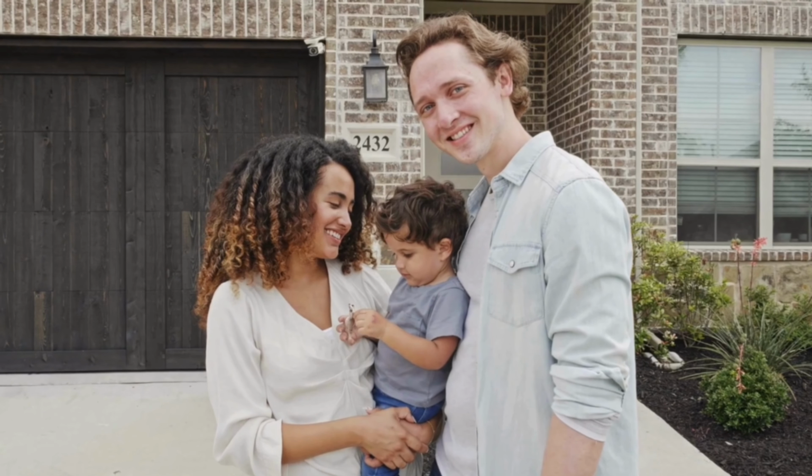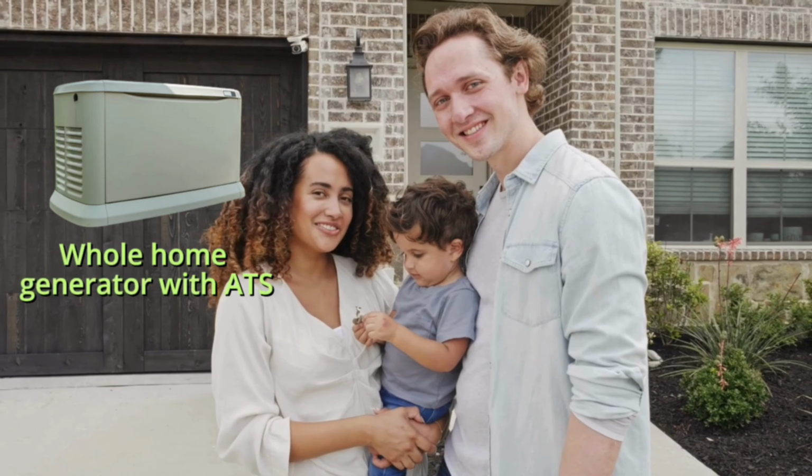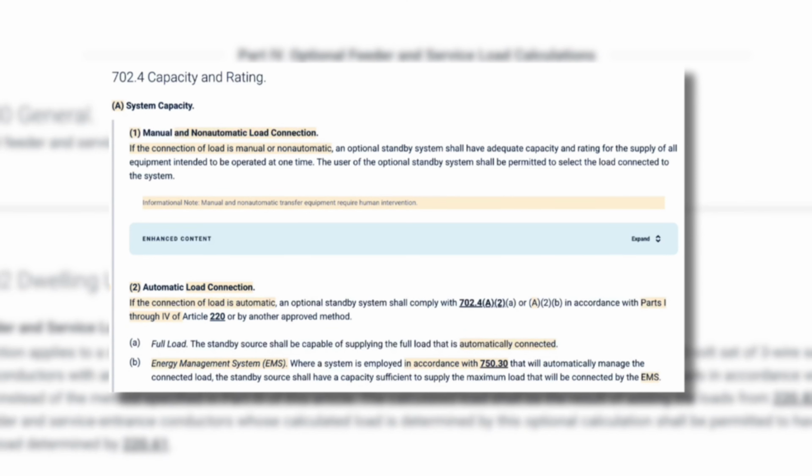Today, we're helping a homeowner in coastal North Carolina who's looking to get through storm season by adding a whole home generator with an automatic transfer switch. Because they want an automatic transfer switch, NEC 702.4 applies. This states that when an automatic transfer equipment or automatic load connection is used, the standby source shall be capable of supplying the full load that is transferred. This means the generator needs to handle the full load of the house as calculated by an approved method like an Article 220 load calc. So let's build a load calc to figure out exactly what size generator they'll need.